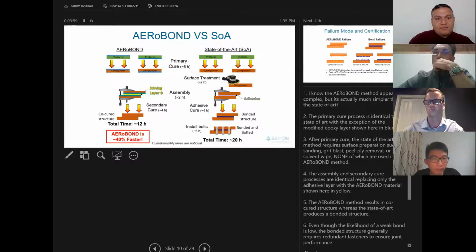That's a pretty good question. We haven't studied how long the surface is stable, but once the part comes out of the autoclave from the primary cure, we've had experiences between 1 day and a week, and we haven't seen that as a variable of significant importance. On top of that, that partially cured surface doesn't have a Tg anywhere near the Tg of the bulk laminate, which might be close to 200C. If it's a 350F cure material, or 177C cure epoxy, the surface probably has a glass transition around 30 degrees C, so it's glassy at room temperature. Unless you have a really hot working environment, it's a glassy material. Because it's glassy, there's not really any progression of the polymer to a higher molecular weight in gel. Okay, that's awesome.